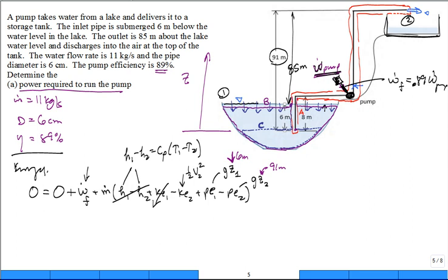So now, what does this equation look like? We have W dot into the fluid is equal to the mass flow rate times G Z2 minus Z1 plus 1/2 V2 squared. I know I have a negative sign that I flipped around over there because I wanted the work on the left-hand side, equal to a lot of it on the right-hand side. But I'm going to pause. Does that equation look good? Do you see how you got it? Yes. Can you read it?